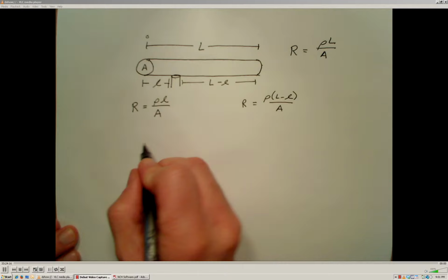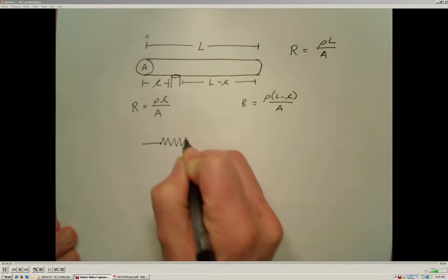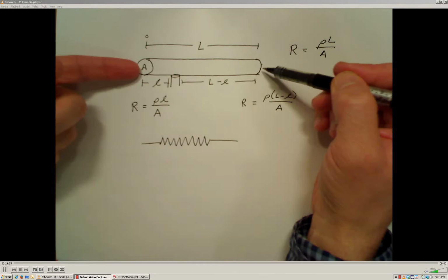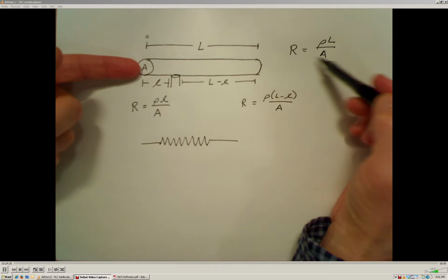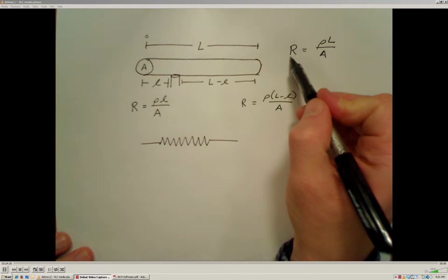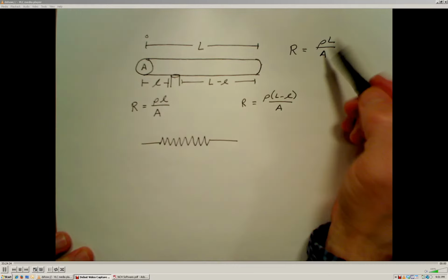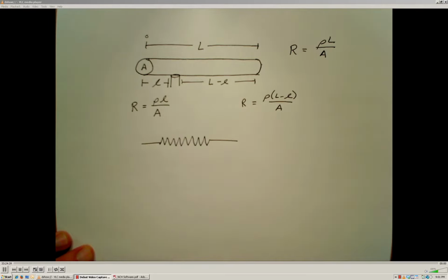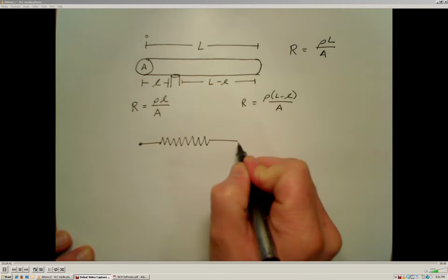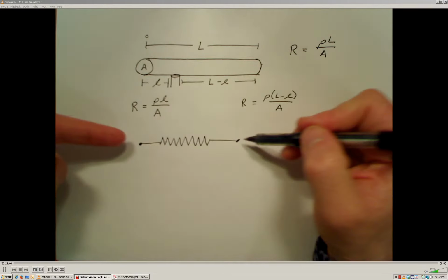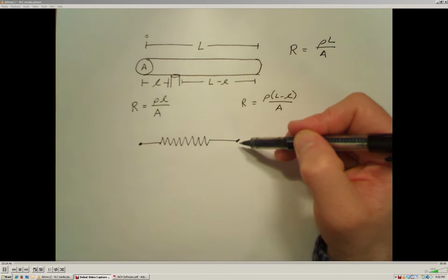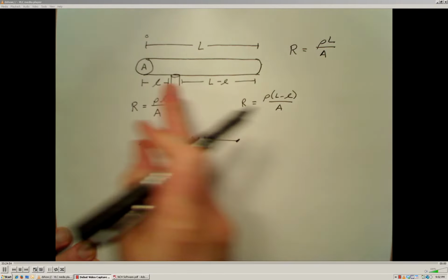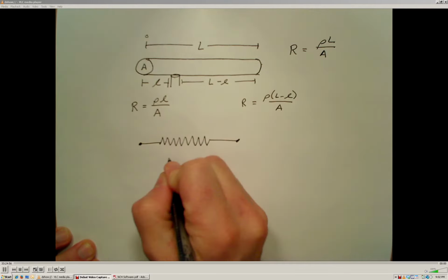The potentiometer is a three-terminal electronic device, and we represent it as a resistive element. In between two of the terminals, the resistance is fixed and remains the same value the entire time, because the total resistance along this entire length is dependent upon the resistivity, the length, and the cross-sectional area of the material. So that's two terminals. If you measure the resistance between two terminals, it's always going to remain fixed. A third terminal is then added, and that's a movable terminal called the wiper terminal.